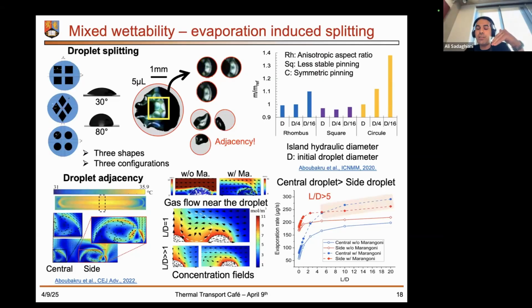So for this, we linked COMSOL Multiphysics with MATLAB, and there were some challenges related to the slip boundary condition, whether we have any changes in the vapor phase on top of the liquid or not, and some challenges related to interface temperature. So these are all continuum modeling.